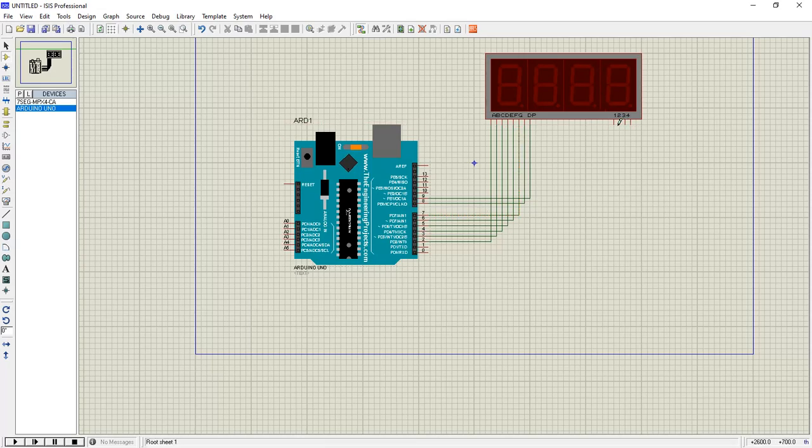And coming to these common pins, generally if it is an individual segment, we will go with anode and cathode, which means VCC or ground. But now here I am connecting with IO lines, whereas in real hardware, you need to manage these common lines with transistors, as the data lines are connected with the IO port. So this is the connection required if you are handling maybe 4 digit or 6 digit or 8 digit common anode or common cathode 7 segments.